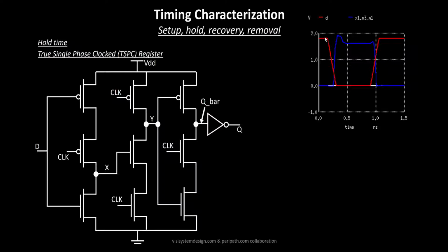For example, initially your D input was 0, then logic 1, then it goes to logic 0 and then logic 1. So ideally if your clock was equal to 0, this particular transistor is basically turned on, and this thing works as an inverter. So whatever you see at the D, X is exactly the inversion of it, of the input.